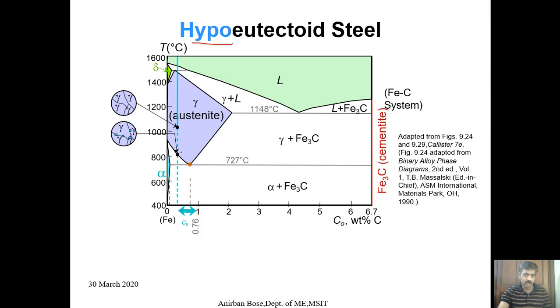That means this is already solid, but the formation of another phase, the alpha phase, started. Where does this alpha phase formation start? Around the grain boundaries, because grain boundaries are the defective regions where free energies are larger, and by forming this, the free energy will be reduced. So there is a spontaneous tendency that this alpha phase will start forming around the grain boundaries.